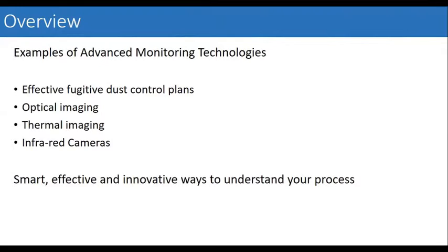Additionally, you could take a look at equipment to see if there are places where there is increased friction. It will usually be depicted by a temperature differential, and that might mean that the increased friction would ultimately lead to failure within that system. So just as a precautionary, proactive look towards maintenance.